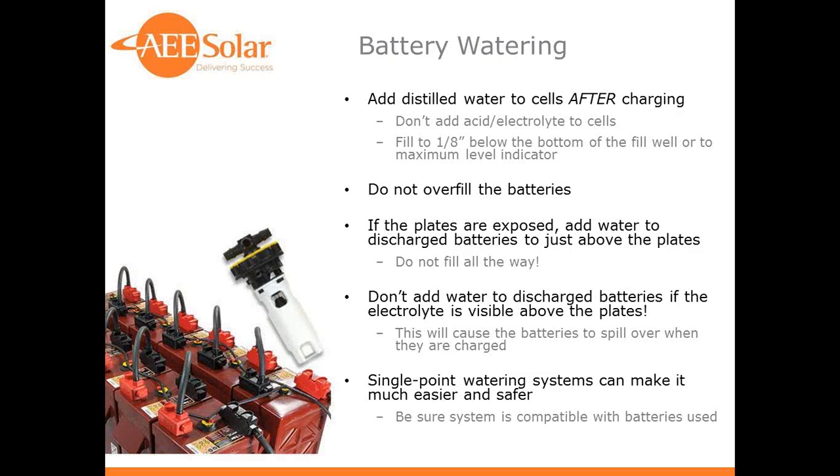These systems are not completely automated. You do need to manually turn them on and turn them off, and the reason for that is that they're based on replacement caps that have float valves in them. And a float valve, as anyone knows in the real world, can actually stick. There could be some corrosion in there or some dirt in there, or it can just stick somehow, and you could have an overflowed battery and an acid spill. So somebody needs to be on hand to monitor the system and make sure it's functioning properly.